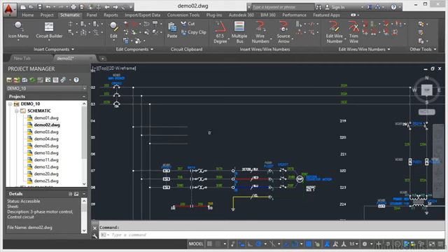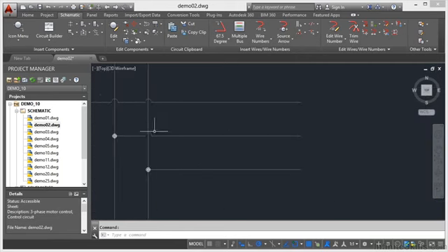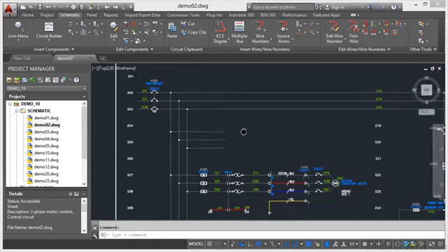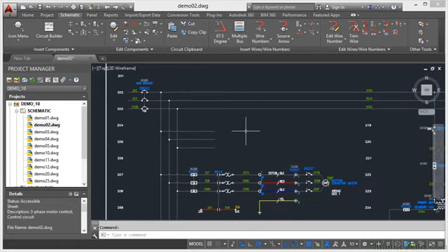So let's have a quick look at what we've placed. Let's zoom in. You can see where I've joined this 3-phase bus here to the vertical 3-phase bus there. There's my connectors, there's my wire gap loops, all nicely and neatly placed for me. So that's why you use your multiple bus connections when you need multiple phase wiring.